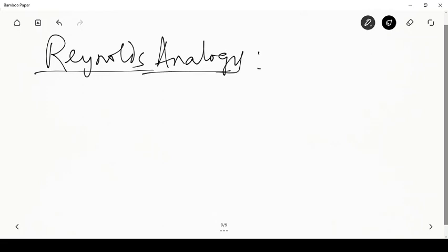So this happens when Prandtl number is equal to 1 and Schmidt number is equal to 1. So the 1 over RePr and 1 over ReSc become identically equal to 1 over Re in the momentum equation and the species equation. Then the mechanisms of transport of momentum, mass and energy are identical, and their magnitudes in the non-dimensional form are also identical, because their boundary values are 0 at the wall and 1 in the free stream for all these quantities, and therefore they have exactly the same solutions.